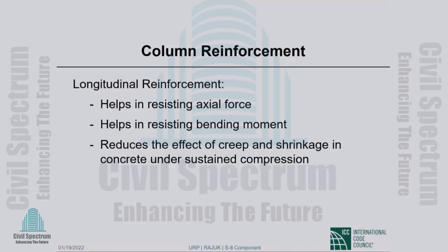Shrinkage, you know, is the evaporation of water out of the concrete, a load-independent phenomenon. Creep is a load-dependent phenomenon. If you keep a compression on a member, the immediate deflection due to the compression load will increase with time, and the time-dependent increase is called creep.